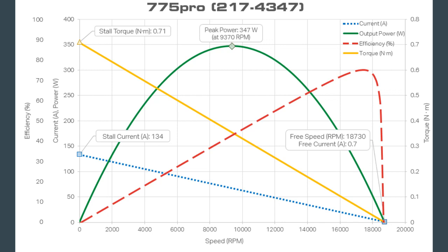So you have kind of more you can give. Also, when you're inefficient, the motor heats up, and then it's even less efficient because hot wires are less conductive. So you basically do not want to get to the point where you're running away with it. You don't want to get past the halfway point.